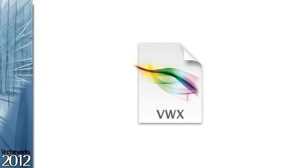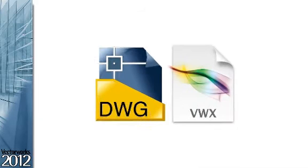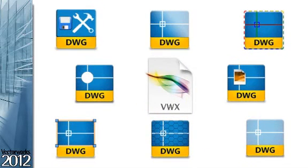And as I'm sure you're aware, it's more important than ever to communicate effectively with your colleagues and other team members. We've made great strides with our DXF DWG support so that you can collaborate with ease. Save your export settings. Gradients can now be imported and exported. Line weight by color has been improved. Clip blocks are now a choice. Image fills are a great addition to the list, as is export only selected objects. Import hatch has been improved, and finally, opacity is accurately translated between CAD applications.